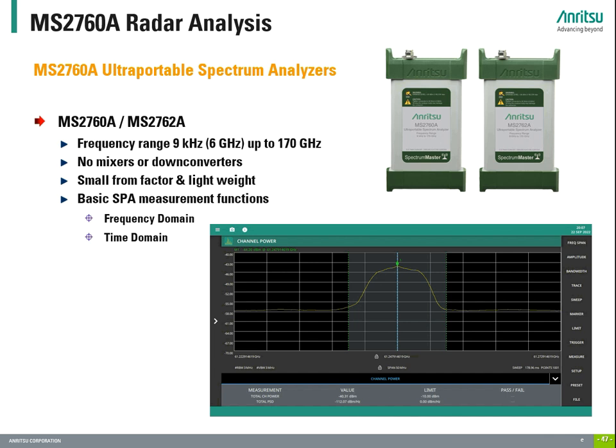Due to the small form factor and the used non-linear transmission line architecture, the NLTL sampler is a technology that enables higher frequencies, but cannot offer us IQ capabilities.